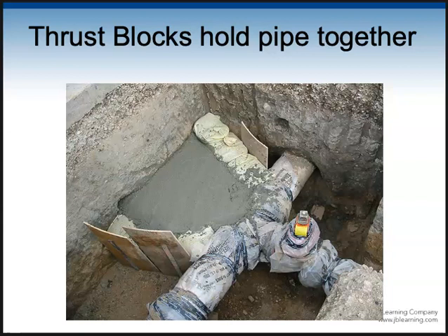Basically the plumbing is all stuck together, where you'll have a male end that fits into a female end, a bell housing, and they just squeeze it in there. Now the problem is, if you didn't restrain it some way, as soon as you put water and pressure in there, they'd all just pop out and explode and fall apart, with water shooting everywhere.